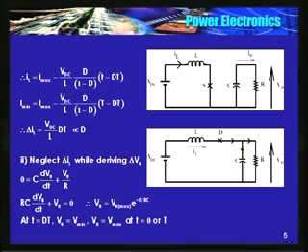So this is the equation for the output voltage when the switch is closed. At t is equal to dt, just prior to opening the switch, the capacitor voltage has attained the minimum, because the moment I open the switch, the capacitor starts charging.